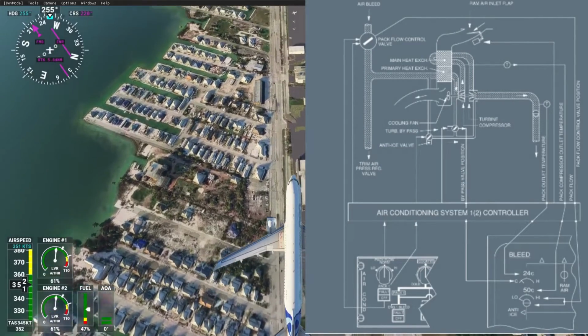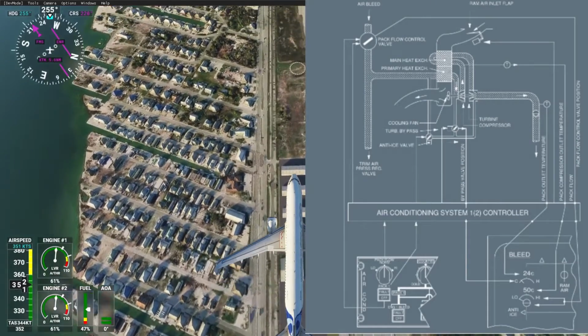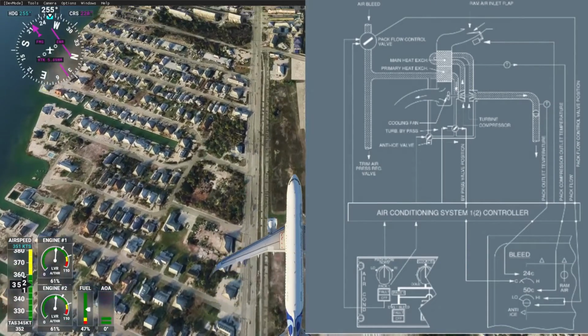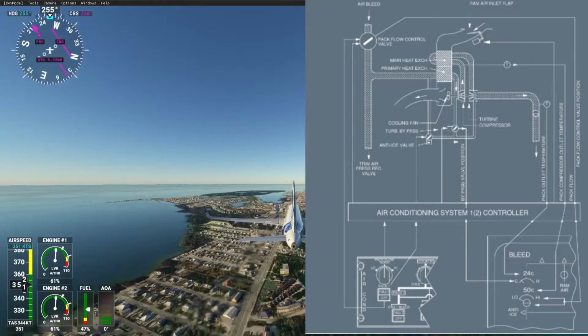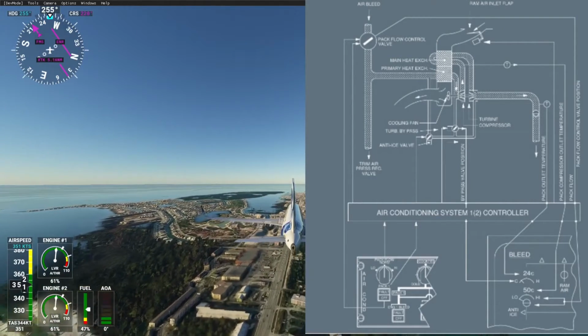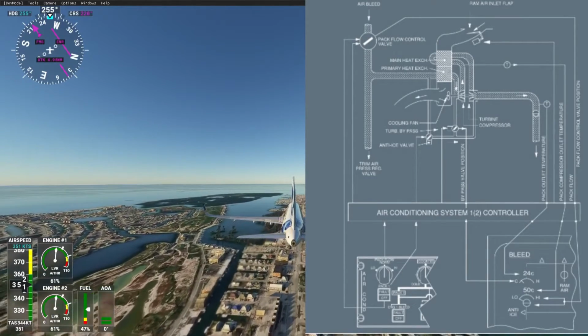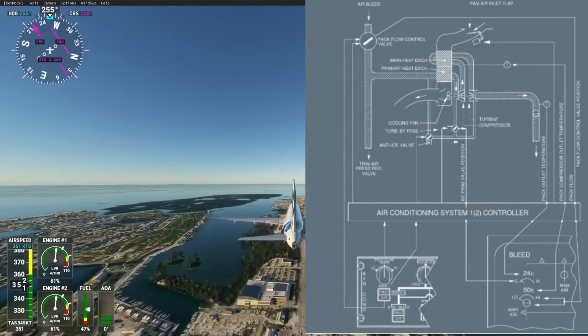Also worthy of note is the aircraft is capable of opening valves that are able to bypass different sections of the pack if it needs to. And the air used in the heat exchangers is taken from outside the air pack using a ram air inlet, which is not the same as the emergency ram air. This is a different inlet.